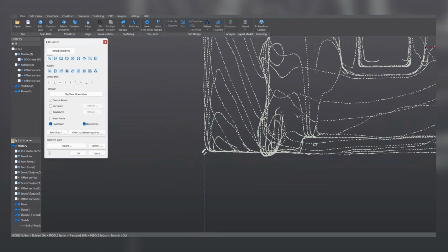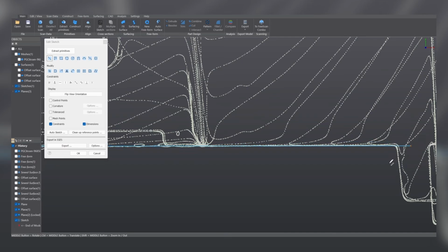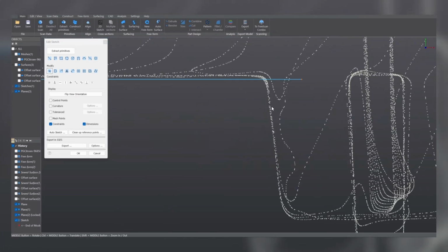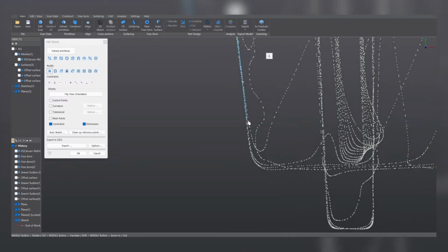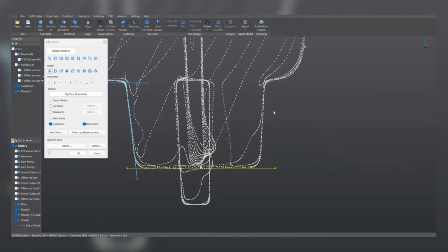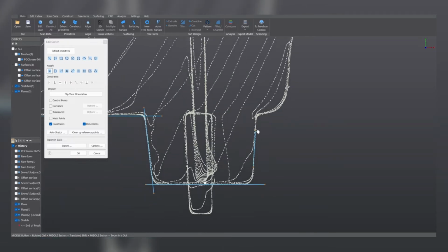Now, what we do is, let's start here in the origin. Let's draw a horizontal line like this. Actually, let's click on it and make sure that it's horizontal. And now let's reproduce this geometry. How? Well, with the Shift key and selecting the points, you can quickly best fit lines. Here, actually, I will eyeball one horizontal line on the top of this shape. Here, let's also best fit a line, like so.